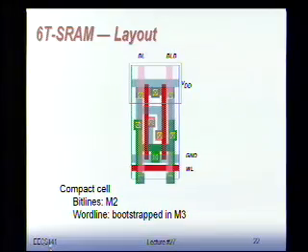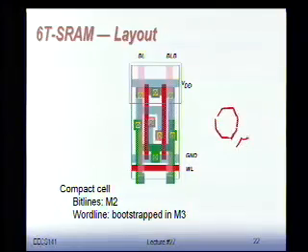The way they do this is, well, there's some design rules that says I cannot put this thing too close to it, but nah, I know it's going to work. If under a certain condition, I'm going to analyze it very carefully, I'm going to violate some of the design rules. I'm going to put things closer than I should. Or very often, if you look at the most fancy designs, they're going to do very interesting things. They're going to have contacts which are hexagonal. They cut off the corners, because then if I cut a corner, I can put something closer again to it, and I can compact everything a little bit closer together.